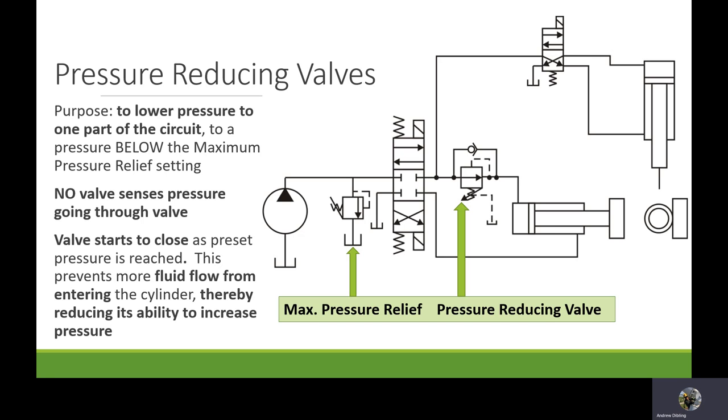Right? As the pressure goes this way, the first thing it's going to do is come to this one, which is going to block the flow from this cylinder right here. So as the flow comes through, it can't go against the check valve. This is a normally open valve, so it starts to build pressure on this side. As this moves and pinches against the piece here, the pressure will rise once it's pushing against resistance. That will allow fluid to come back through the pilot line and close the valve. Any extra fluid will get pumped through the check valve.